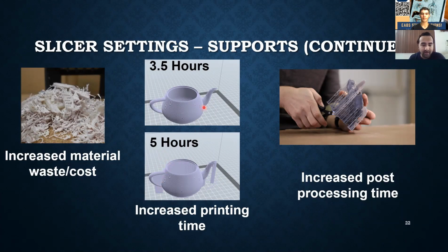And if you look here, you have sort of this curve that's occurring here, which seems to be fairly sub 45 degrees, maybe except for this point right here, but you might be able to get away with it. And you have this nice curve up in here, except for maybe this inner part here that's floating. So if you intelligently make your supports, you may be able to get away with only having to put supports inside here and maybe only at the tip here. And you can get away with not having to put supports everywhere. And naturally, because the supports are inherently part of your structure, you have to remove them afterwards with clippers and such. So it's always just a pain.